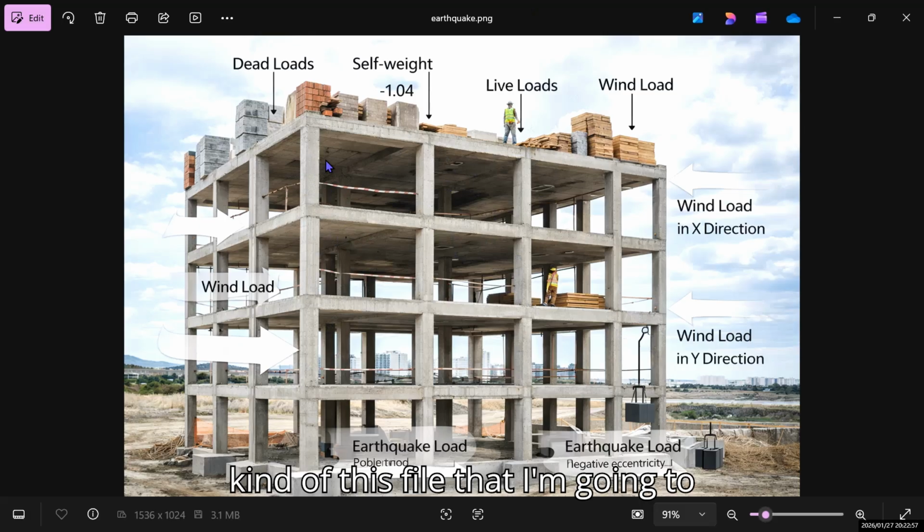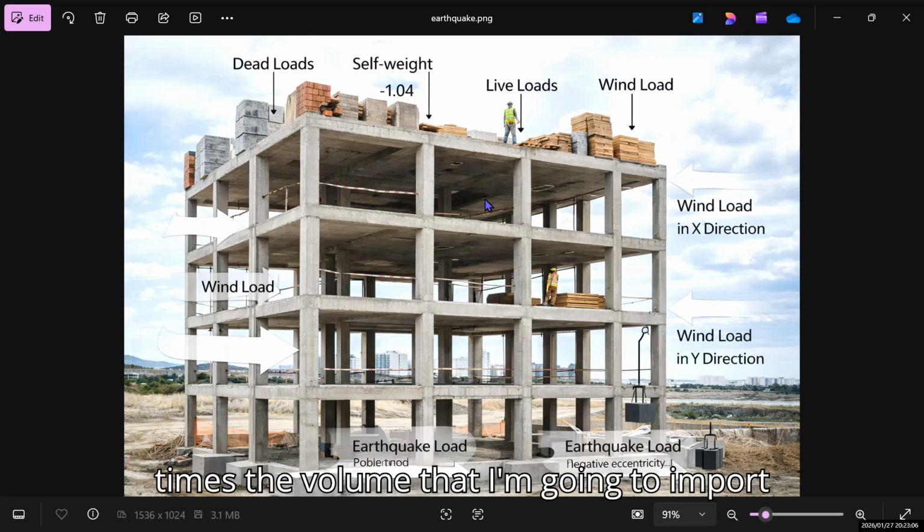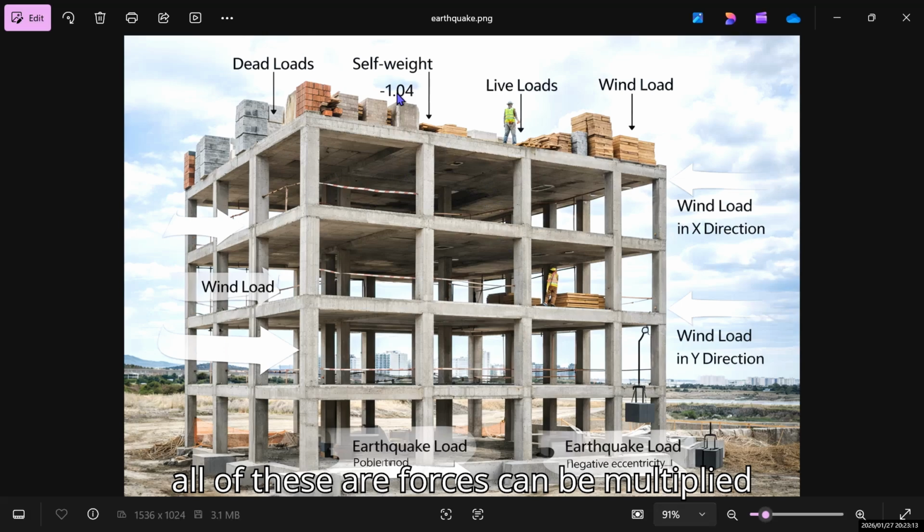This value is going to calculate all of the weight of this building times the value that I input, negative 1.04. All of these forces are going to be multiplied by negative 1.04. So you have to make sure that this is really included in your structure.